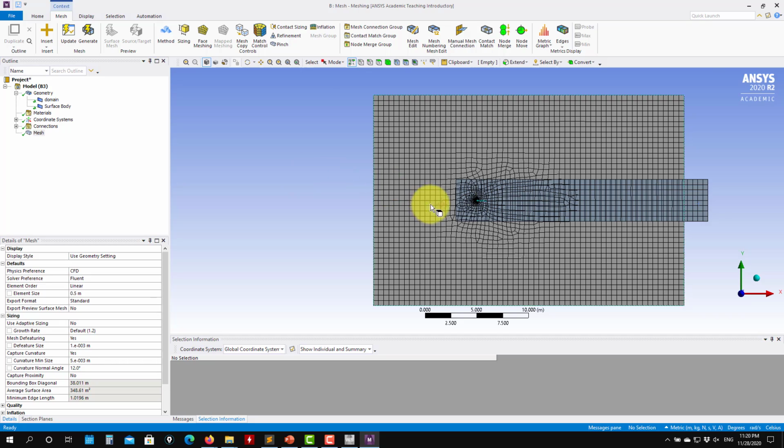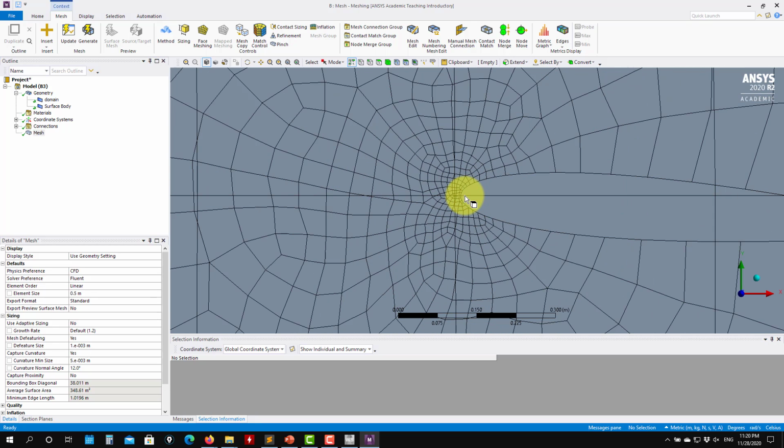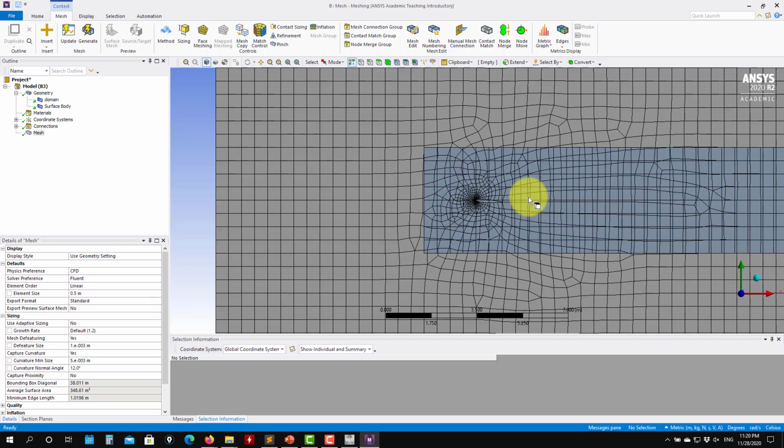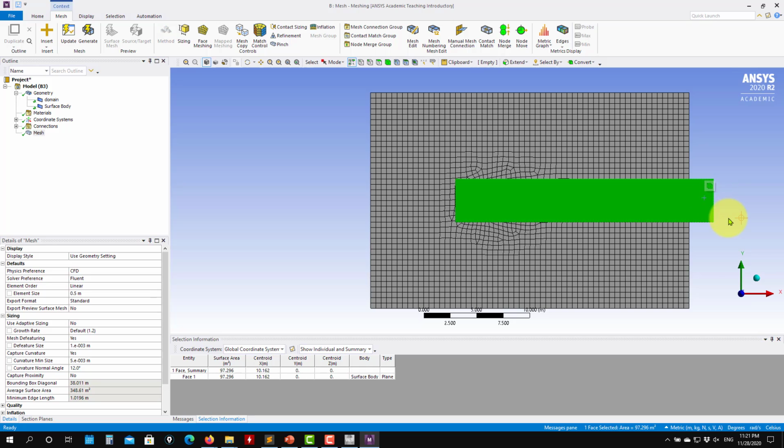Okay, there are different methods. See that where you have more curvature it is putting more elements, as we know, that was controlled using the global options. But see what is happening here: we wanted to use this external rectangle to control the refinement in that region, but it's doing two meshes. So now we need to tell Ansys Mesher that this external one is used to do a body of influence. Okay, so we need to add now local refinements.